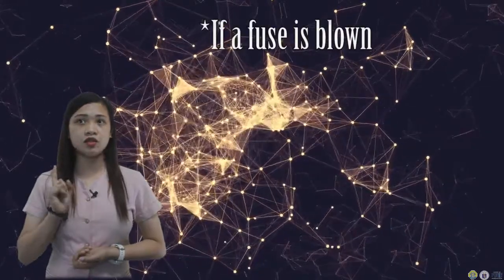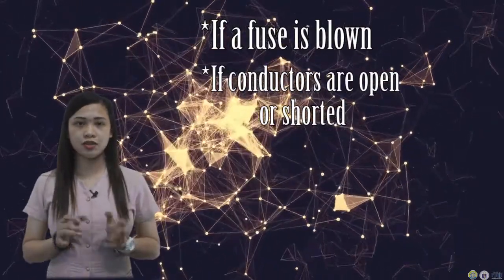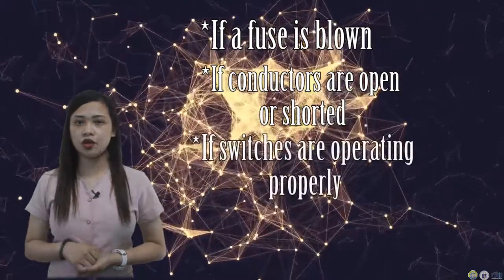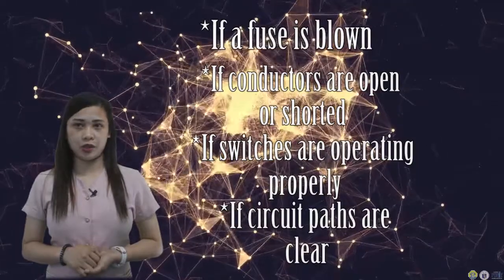Continuity testing determines if a fuse is blown, if conductors are open or shorted, if switches are operating properly, and if circuit paths are clear. Continuity testing should be attempted only when voltage is not present within the circuit being tested.